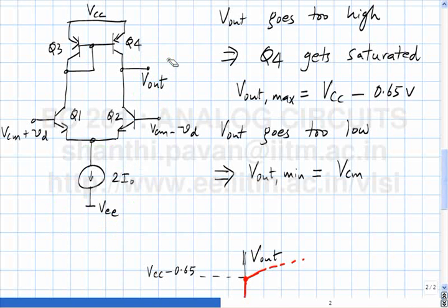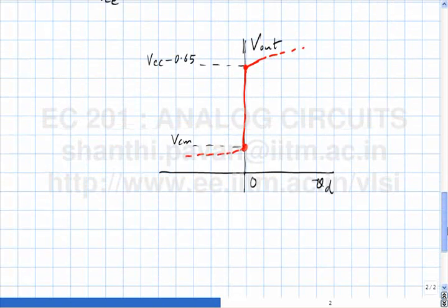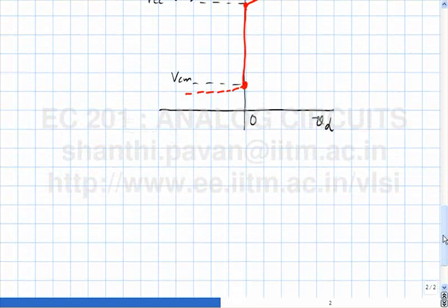If the output impedance is not infinity, you draw the equivalent circuit and you will get a common mode rejection ratio of the form GM times 2 RS or RT, whatever we called it. As the output impedance of the tail current source becomes larger and larger, the common mode rejection ratio approaches infinity. Is that clear?